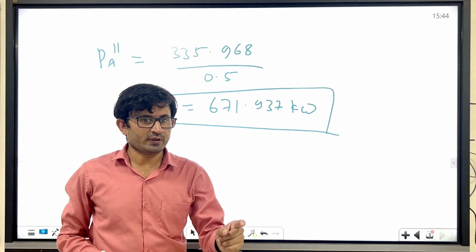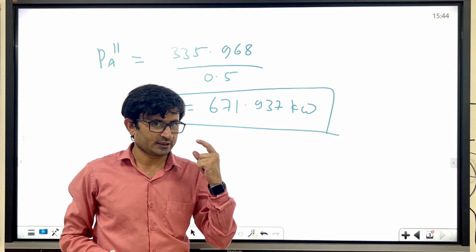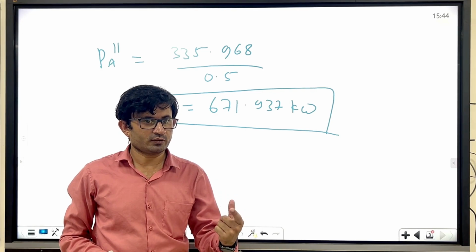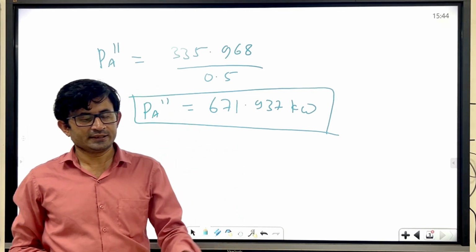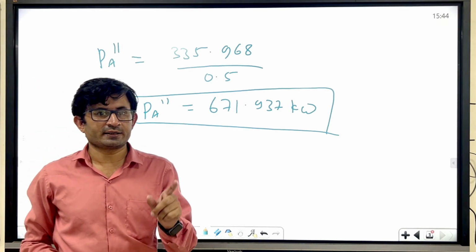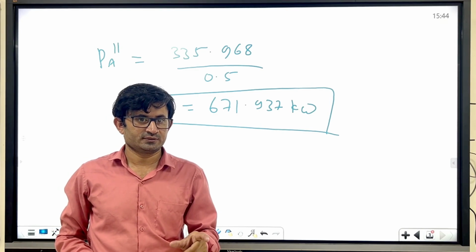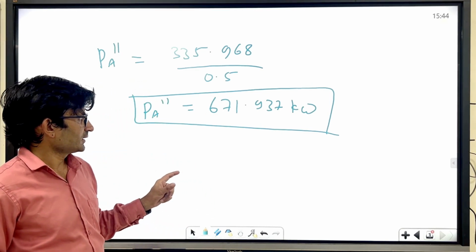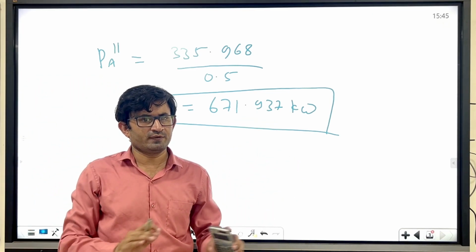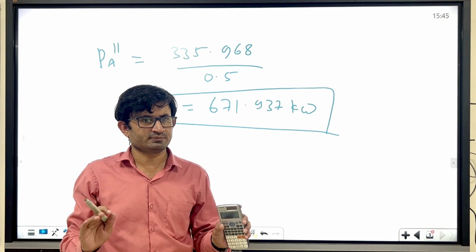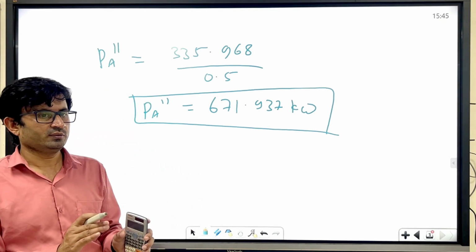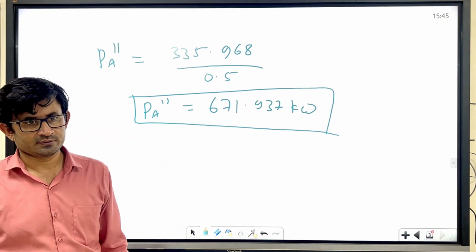Based on the climb requirement, you calculate the power required to perform a climb, and then you can also check if you want to fly at the Vmax condition. Then you may go back again to the cruise condition and put Vmax. Among all, where the power required is maximum, you have to consider that value and select the engine accordingly. Okay, thank you.